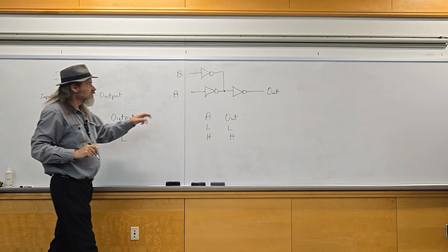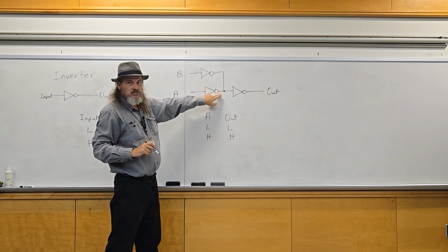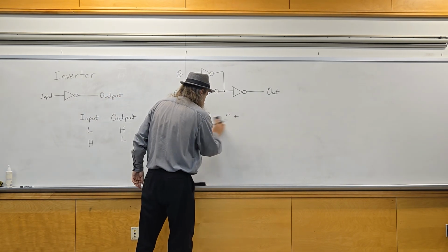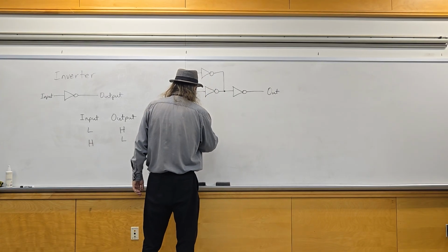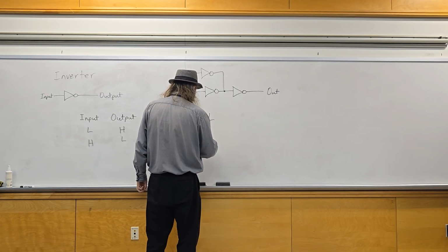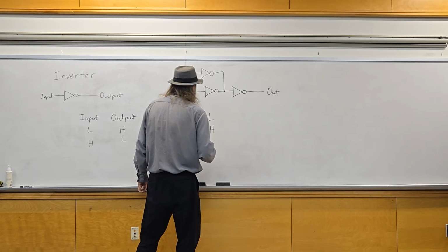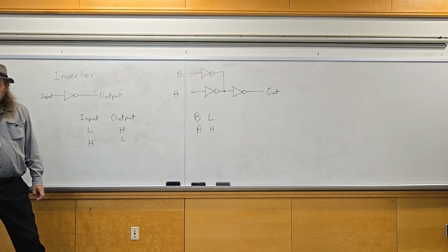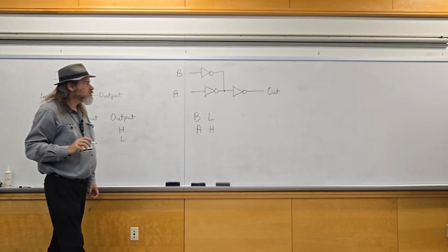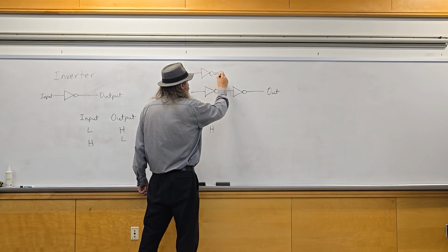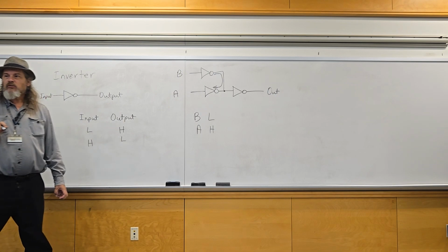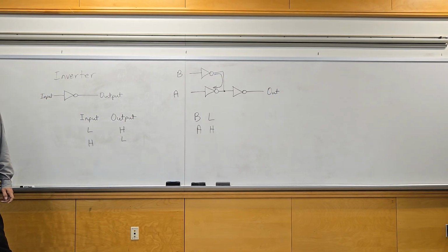You don't link outputs together, because in this situation, if B is low and A is high, what will happen? A short circuit. Exactly. You'll have a high signal here going to a low signal here, and things will start smoking, and we all know smoking is bad for you. In the lab especially. Things blow up, catch fire, that sort of thing.